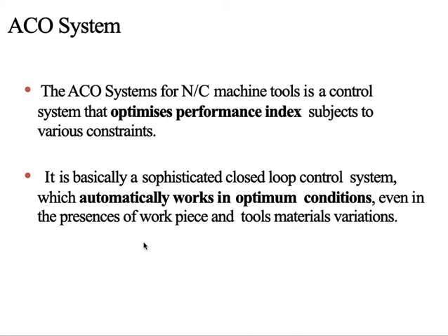The figure of merit is called the merit function, which is a numerical measure of efficiency. The magnitude of a figure of merit indicates the merit or desirability of the given combination of process variables. The figure of merit is the production rate or cost per volume of the metal removed.